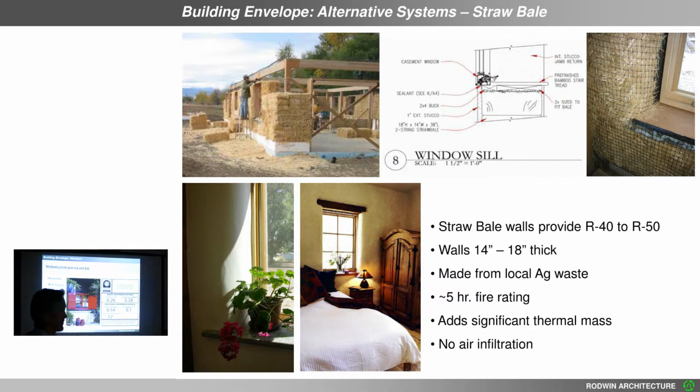Are the most successful straw bales with a timber frame support? There are several different ways to do it. You can do load-bearing straw bale if it's a single story. You can do a post and beam. This project that you see right here actually went up 2 stories, where it's a post and beam frame that carries most of the load, and the straw bale is just an envelope that's attached to that frame.